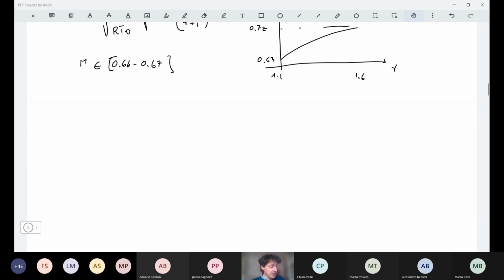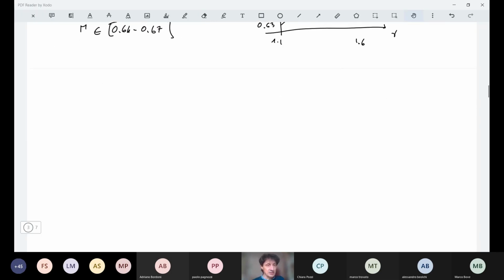So summarizing, for the flow that is exhausted through our convergent nozzle, we can have two possible situations. First one, that PA is greater than the critical pressure, which is (2 over gamma plus 1) to the power gamma over gamma minus 1, times P0.